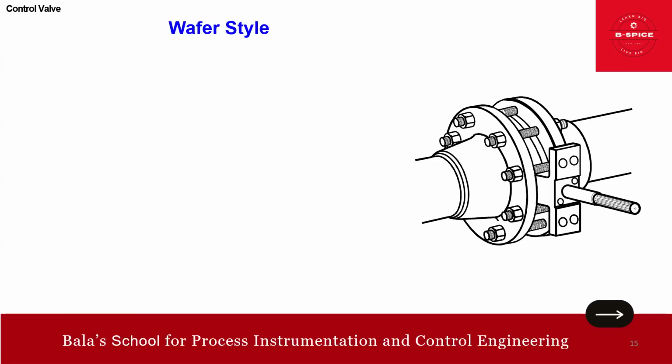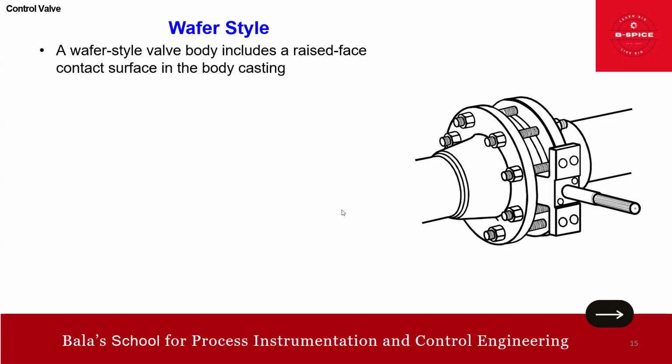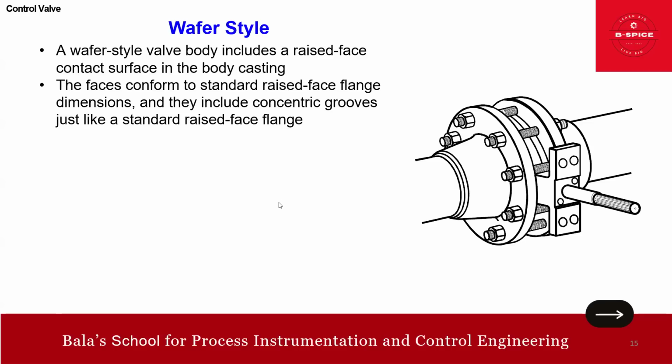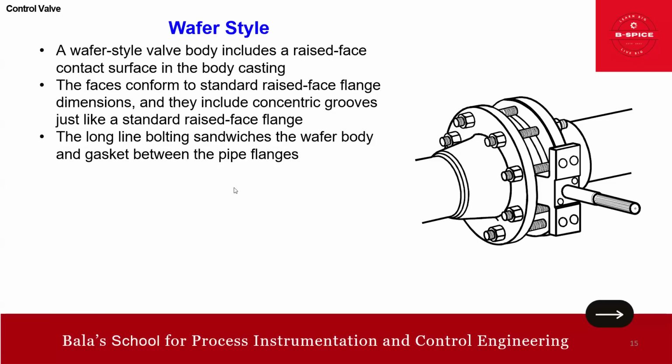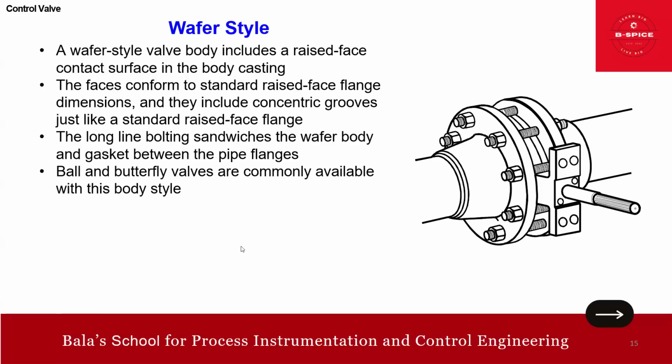Then wafer style, friends. This is the look and feel of the wafer style. See, a wafer style valve body includes a raised face contact surface in the body casting. You can see it here inside, it's a raised face. The face conforms to standard raised face flange dimensions and includes concentric grooves, just like a standard raised face. The line bolting sandwiches the wafer body and gasket between the pipe flanges. You can see the lengthier line bolts, right?